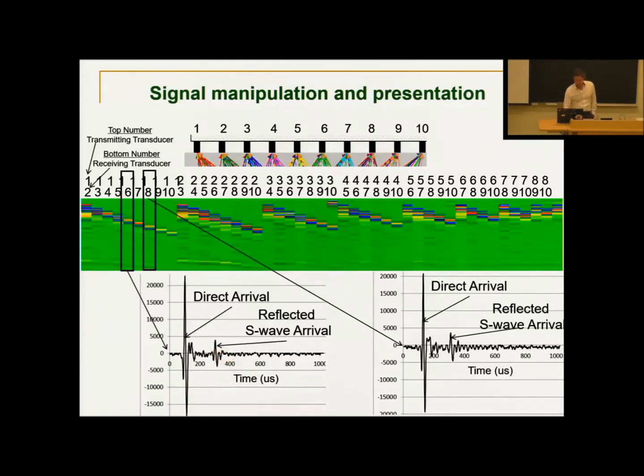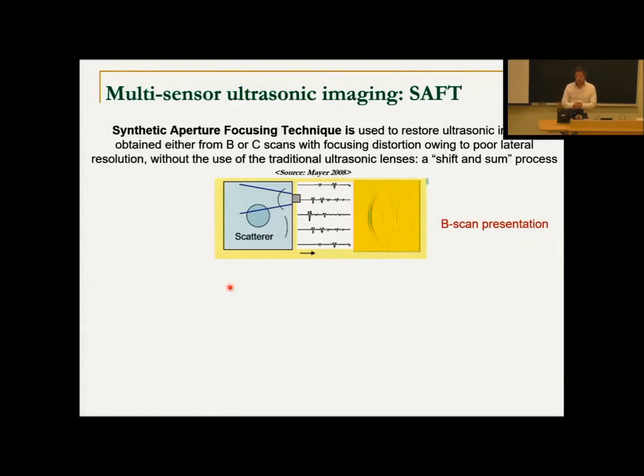And we collect lots of data, which I'm trying to illustrate with this stacked file here. Some of those have these reflected shear wave data. Those are the key, right? Now, once we have these stacks and stacks of data, what can we do with them? Well, we can reconstruct all of these signals using an algorithm to provide a potential cross-section that caused this signal pattern. So we have lots of signals, and we invert that and ask what caused this pattern. That's called inversion.